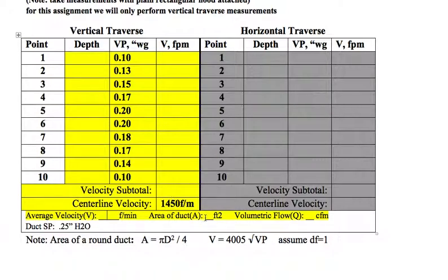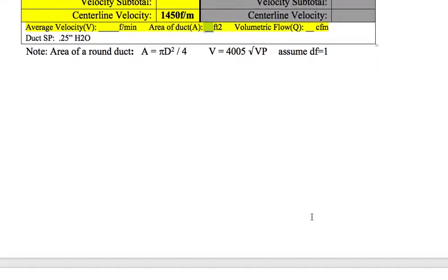The cross-sectional area of the duct you would put in here, and the volumetric flow rate, how many CFM is going through there. And you can use the formula that Q, the quantity of air, is equal to the velocity in feet per minute times the cross-sectional area of the ductwork, or your 6-inch ductwork, or your 0.5-foot diameter ductwork in square feet. Okay, so got to have this in square feet, got to have this in feet per minute, multiply them, gives you the volume of air that's moving through here. So you should be able to take care of that, I think.